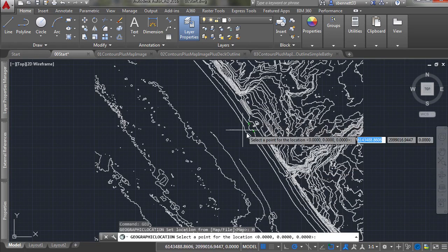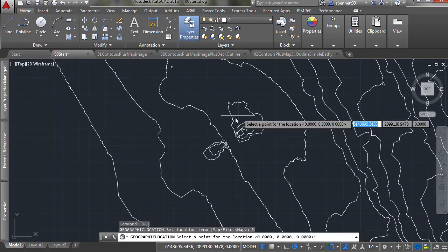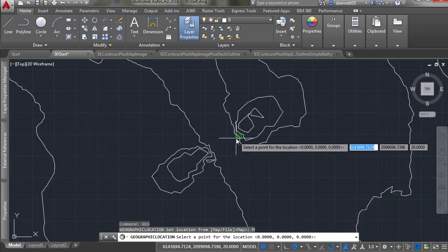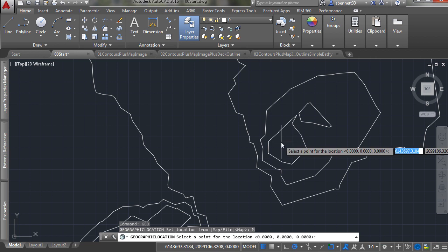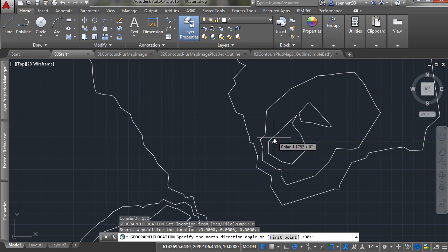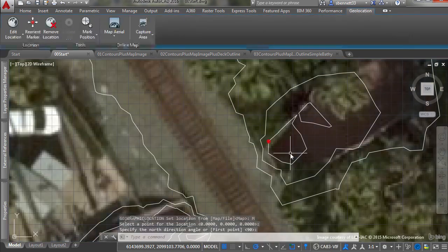First, you'll notice that there's this kind of double lobe feature on the beach, which corresponds to the ramp going down for the tunnel. And we're going to pick an endpoint location. This is mirroring the pin that we put on the map here within AutoCAD. So we'll click on the endpoint there and then hit Enter to finish the command.